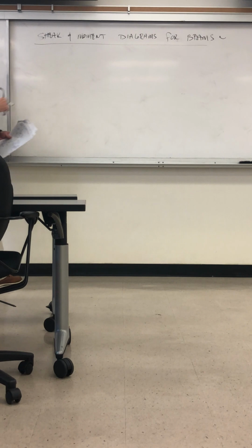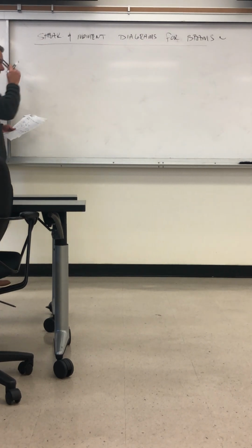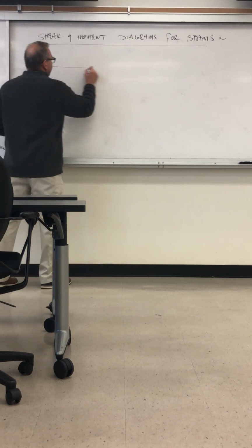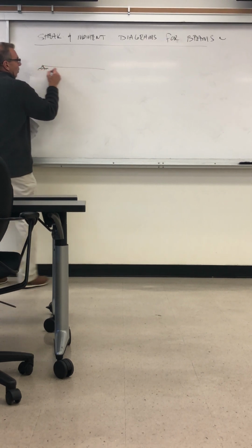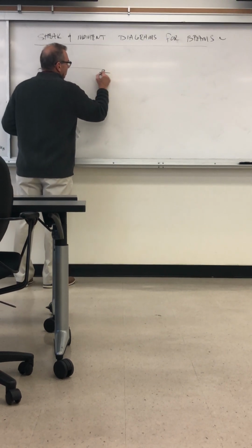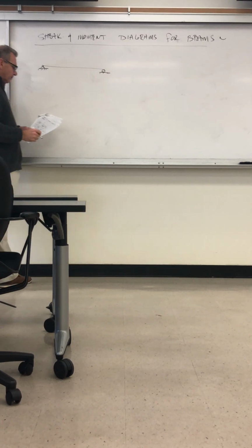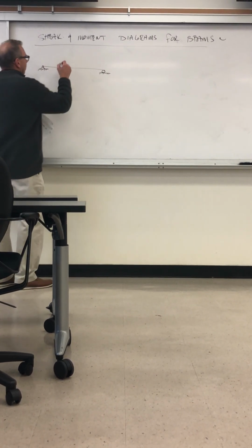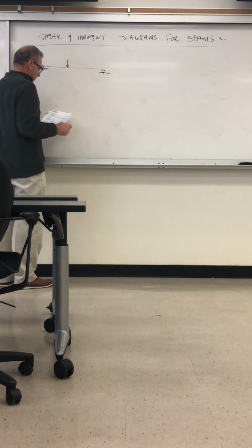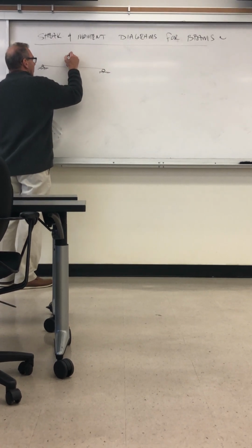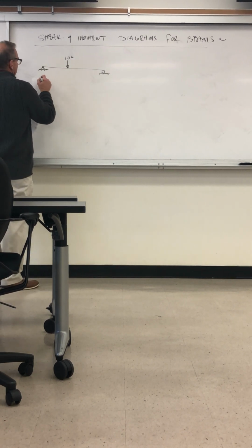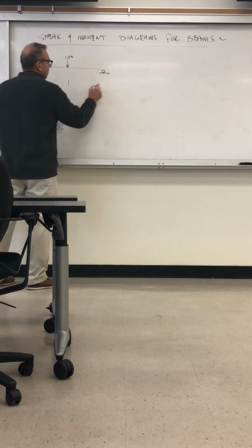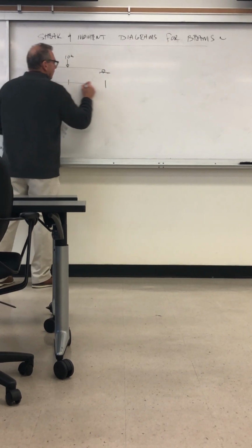So we're going to start simply and then get more advanced. Here's a beam. Again, one side is pinned, the other side's a roller, for the same reasons we talked about before. I'm going to apply a load in the middle, a vertical load, force, 10 kips, so it's 10,000 pounds being applied down. The total length of the structure is 20 feet. This is applied in the middle, so it's 10 feet on each side.